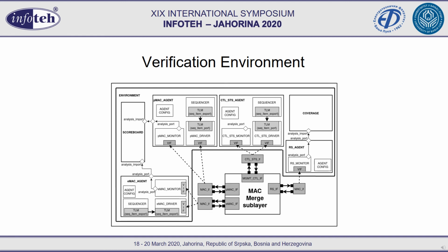Scoreboard component is responsible for comparing the obtained results with the expected results. And coverage module is responsible to give us an answer how many test cases we actually covered by our test.